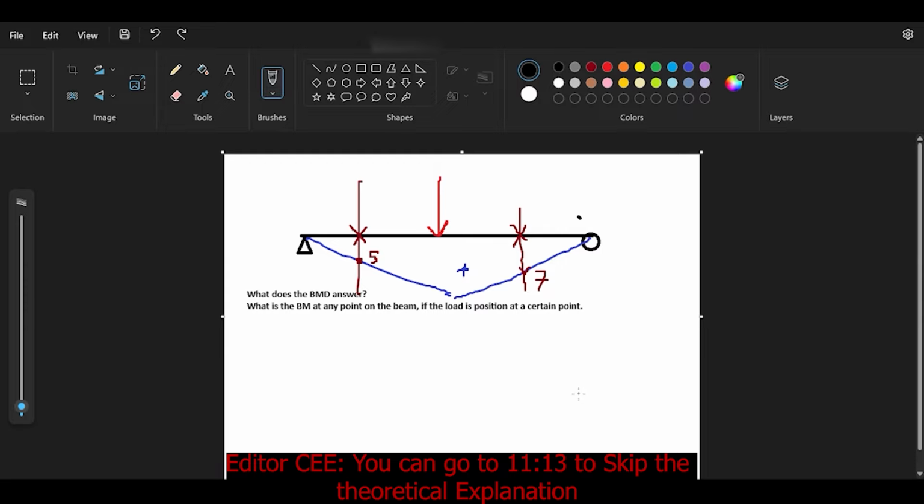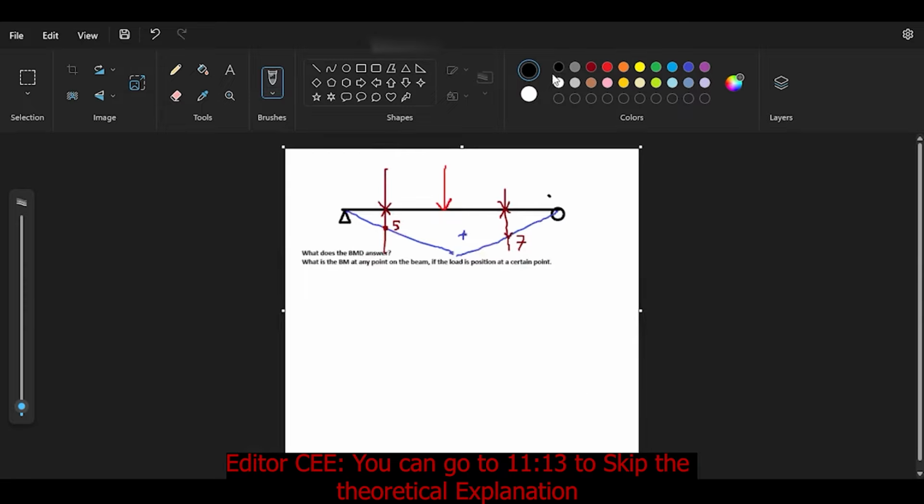Now, what is the influence line? I like to call it the inverse of a bending moment. Allow me to explain. You have, for example, once again, a simply supported beam, and you want to know the influence line for the moment at this point. What you do is, of course, here I'm saying Müller-Breslau. It's a long story. You should learn this from structural analysis books. But according to Müller-Breslau's method of drawing an influence line, you would have to apply two moments like this and bend the beam like this.